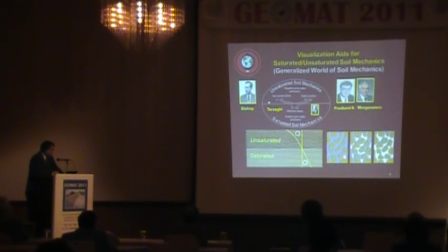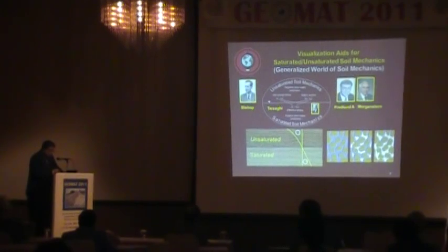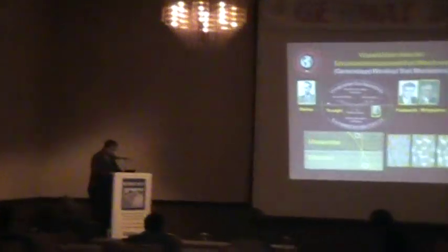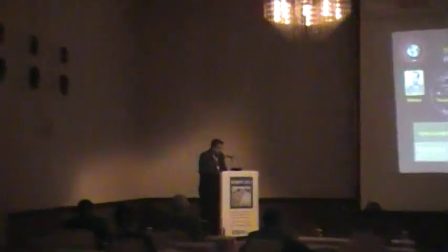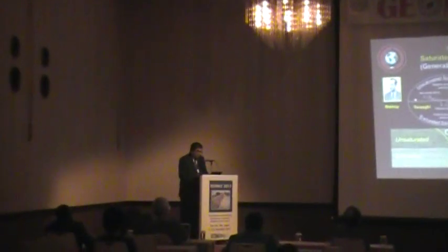Here in saturated conditions, as you can see, all the voids are completely filled with water and you have a two-phase system. But in unsaturated condition, you have the voids filled with water as well as air, and as Professor Oka has introduced, the difference between the air pressure and water pressure is the suction, and this suction can have an important influence on the engineering behavior of unsaturated soils.